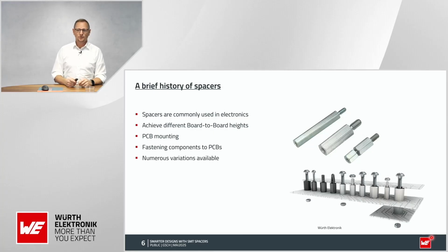Everybody knows spacers, like metal spacers, plastic spacers, or whatever. You can achieve almost every board-to-board height by combining different spacers. It's used in many ways for fastening components to a PCB or the whole PCB into an enclosure. There are so many variations possible, and you can reach a really stable attachment. So it's a very common technology and a very common standard.